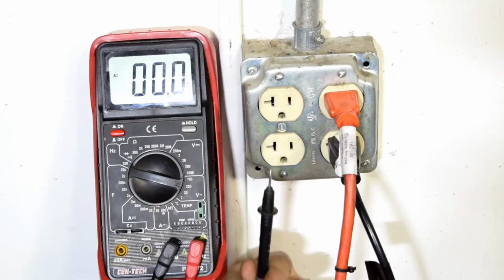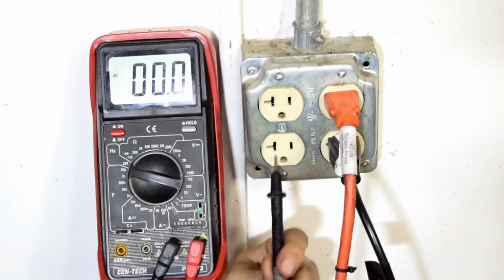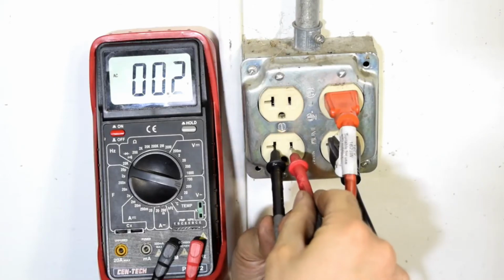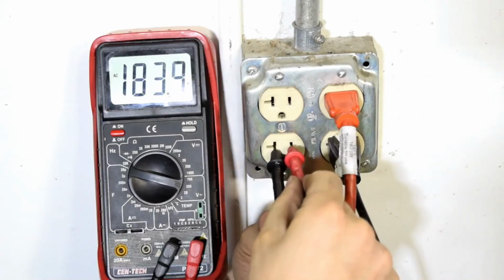Also, when you go to take your measurement, make sure your fingers are away from the tips of the test leads, and when you get near the socket, make sure your test leads don't come into contact or near each other. So next we grab our ground test lead and put it in the bigger slot on our wall socket. Then we grab our red test lead and put it on the other side, which is the power side. As you can see, we got 118 volts coming out of this, which is about right.